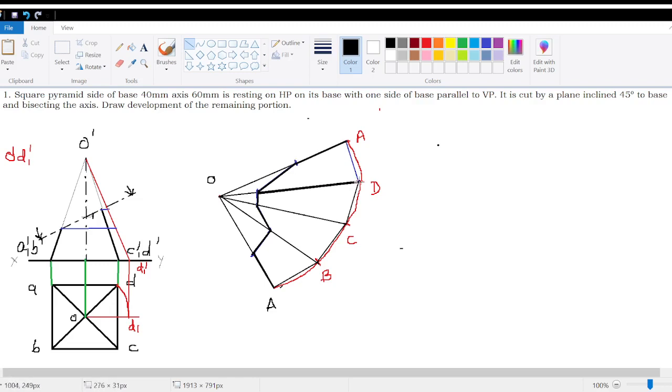So these edges you have to highlight. So I'm drawing it as a very thick line. When you are drawing, it should be 0.5 millimeters only. Each of these lines should be 0.5 millimeters. So better you go for a clutch pencil and use HB lead over it for drawing these areas. And this gives you a final answer. So this area should be extremely light.